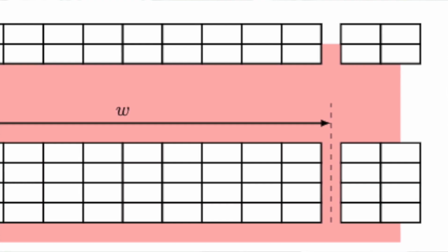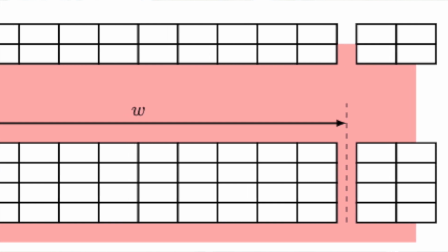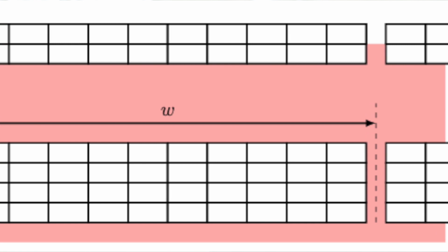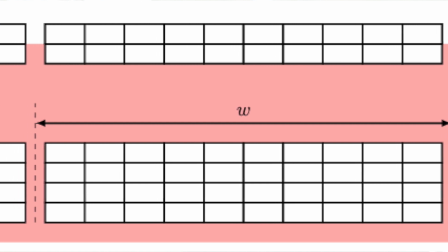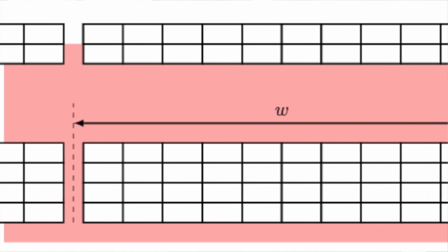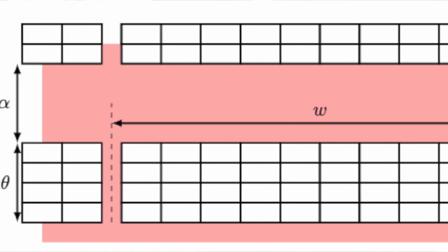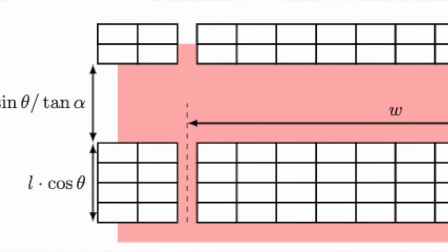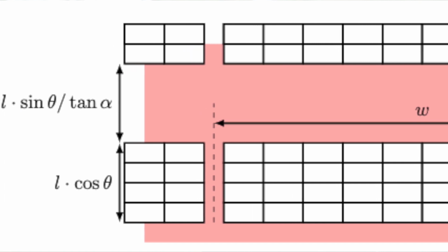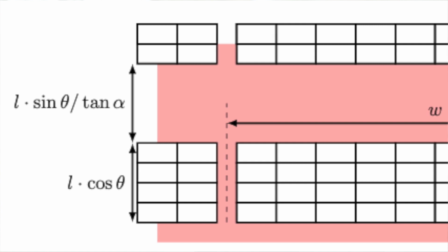So what we have found is that the optimal tilt of the array is directly related to the efficiency of the array that we are using. And by that, we have to take into account the spacing between the modules and the spacing between the tables, because that will derate your effective PV efficiency. So just because you're using 18% efficient modules doesn't mean that your array is 18% efficient, because you have all this space that's used for clamps, inter-row spacing, transformers and so on, that is essentially a derate on your efficiency. So you have to take into account that area in order to know what your effective PV efficiency is. It's essentially the area in your array that is not covered by modules.